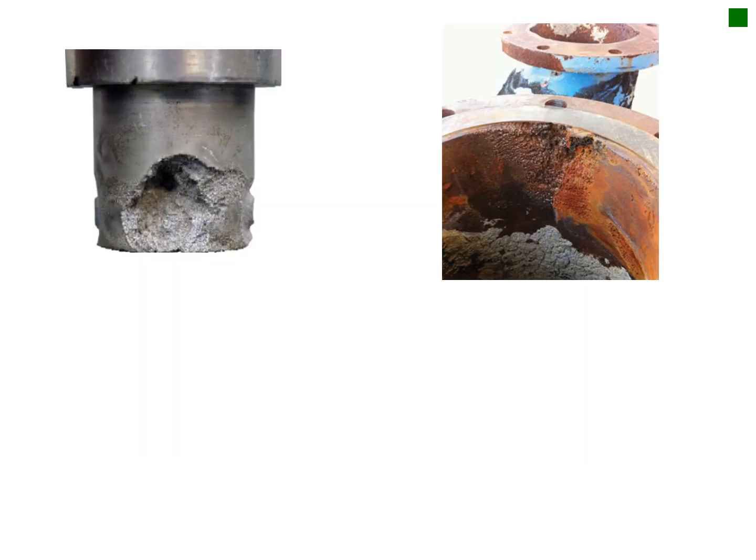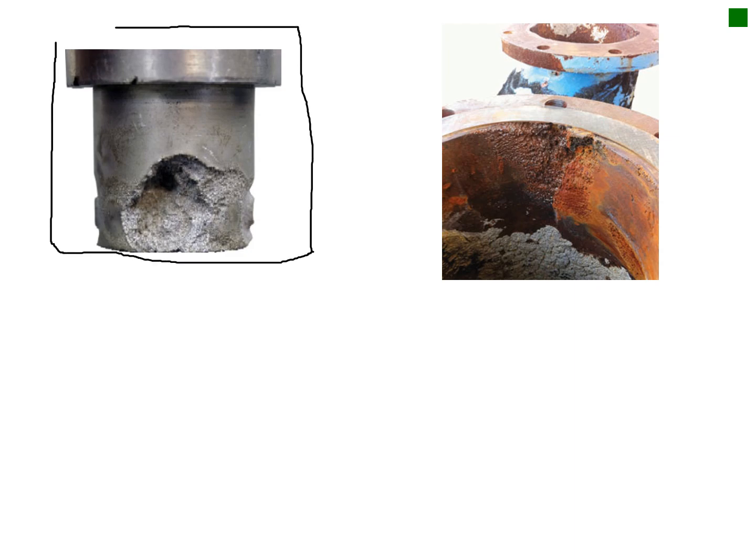One of the things that we have to worry about with cavitation is when the liquid turns into a vapor and then rapidly collapses back into a liquid, we can cause damage to our material. Here we look at the effects of cavitation on a plug in a control valve, and you can see here that collapsing of the bubble actually will remove some of that metal and cause some damage to the valve. And so this can be quite a big problem if we're cavitating a valve.